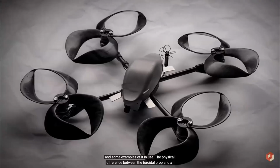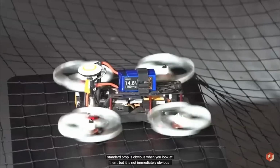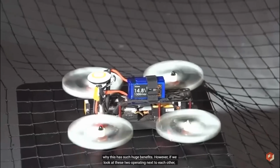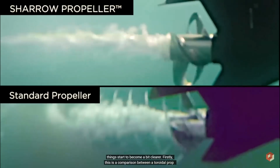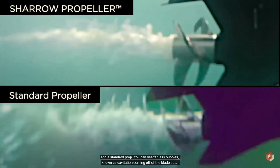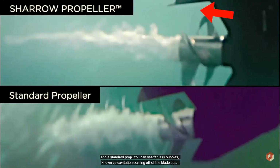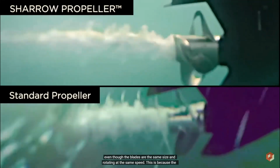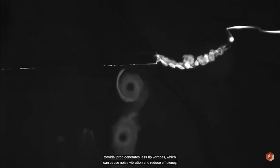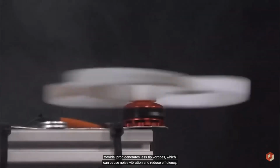The physical difference between the toroidal prop and a standard prop is obvious when you look at them, but it is not immediately obvious why this has such huge benefits. However, if we look at these two operating next to each other, things start to become a bit clearer. Firstly, this is a comparison between a toroidal prop and a standard prop. You can see far less bubbles, known as cavitation, coming off of the blade tips, even though the blades are the same size and rotating at the same speed. This is because the toroidal prop generates less tip vortices, which can cause noise, vibration, and reduce efficiency.